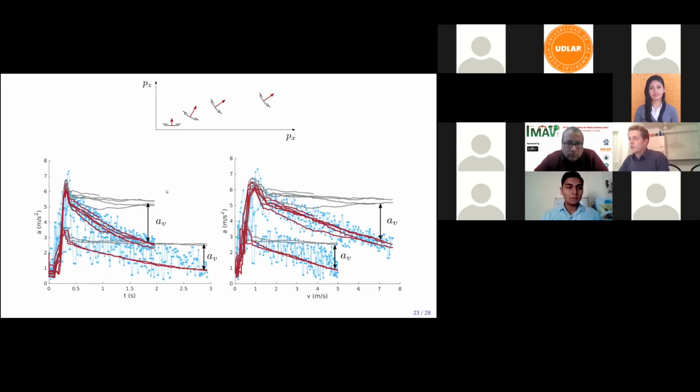And then lastly, the drag behavior, we can also estimate from the roll step experiment. So if we simulate without taking into account drag, we get the gray lines. And if we simulate the same model, but including drag behavior, we get the red lines. And so the difference between them is actually the magnitude of the velocity induced drag. And it is, as we can see here, clearly non-negligible. What's also interesting to note is that even for velocities over 8 meters per second, this linear approximation is still quite accurate, which is also why this linear approximation is frequently used.